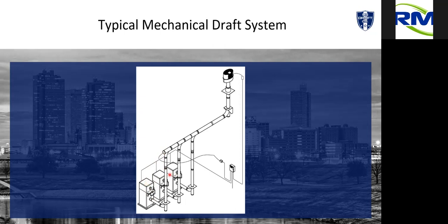So then the second boiler turns on, it does its pre-purge cycle, blows a bunch of cold air into the stack, which changes not only the volume, it also changes the temperature and the pressure. So that pressure actually spikes up, maybe up to a half an inch. And because the controller can't respond to that, it actually creates a blockage in the common vent, which eventually backfeeds and pops the block flue switch on the boiler. The boiler typically will have an air switch on the flue to where if there's a blockage, it will shut the boiler off. So that shuts off boiler 1, but it doesn't block off number 2 yet, so it allows it to go through its pre-purge and fire, okay?